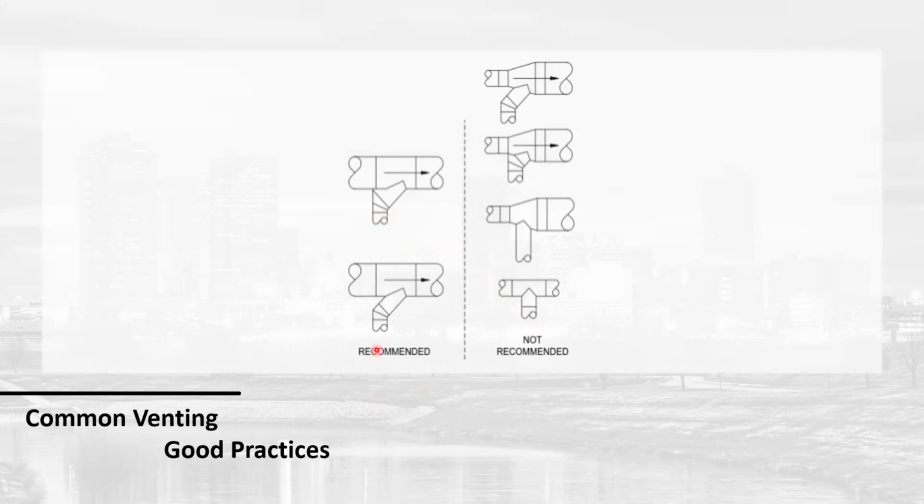You can pretty much get on the ramp and get up to speed as you're getting into traffic with a lateral tee. Here, you have to come to a stop and yield to traffic, and it just kind of opens and you hope for the best. This is just a bad idea. Now, if you don't have the space or if cost is an issue, yes, lateral tees are the most expensive option, but it's the right way to do it. It gives you the best flow, just makes everything work that much better.